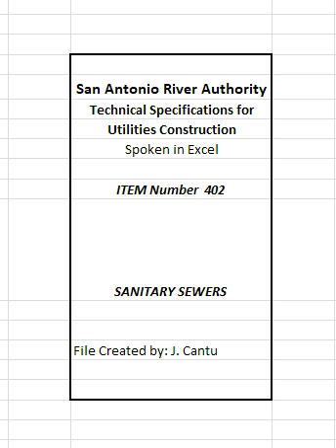If the contractor finds it necessary to install pipe in tunnels not provided on the plans, he shall submit to the engineer, prior to commencement of work, a detailed outline of procedures, methods, and use of materials depending on existing soil conditions. No horizontal or vertical curves shall be permitted in conformance with appropriate regulatory agency requirements.